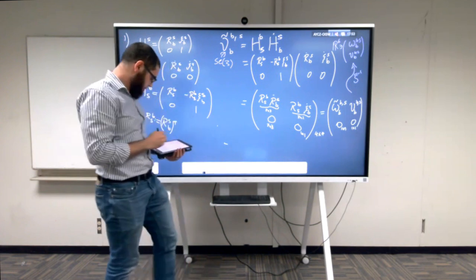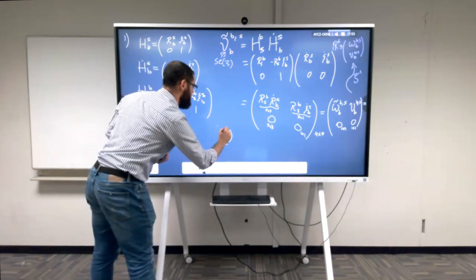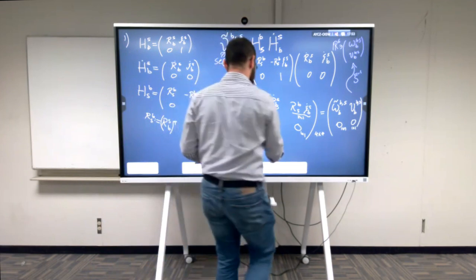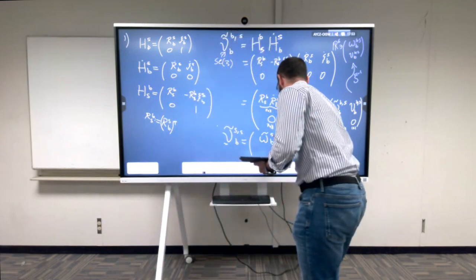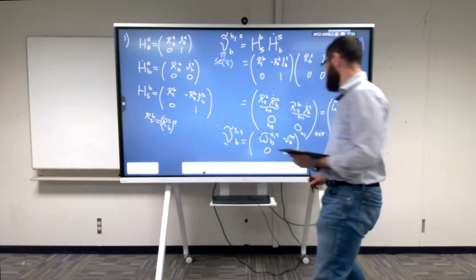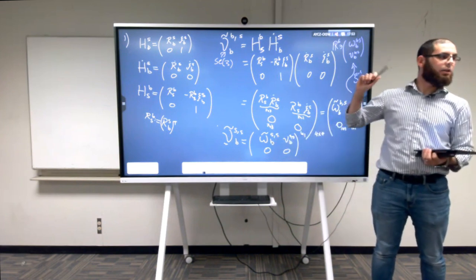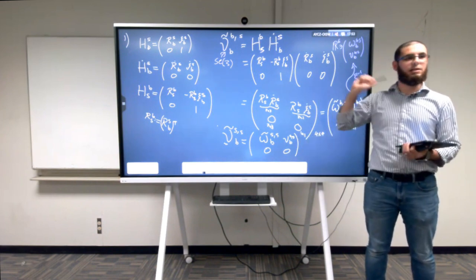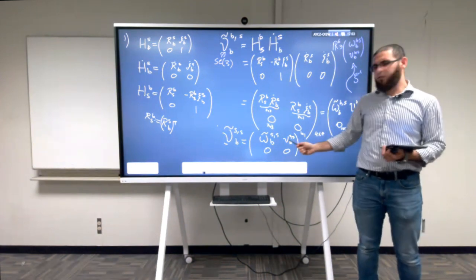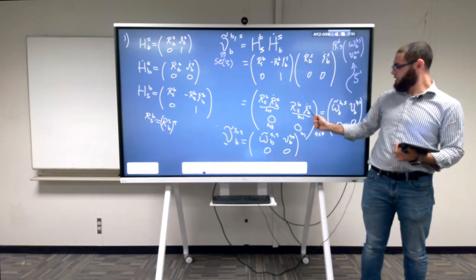This something else, even though it will have different relations, so this V tilde of B with respect to S expressed in S will have omega tilde B of S with respect to S, 0, 0, and VB SS. So again, we're going to have some angular velocity expressed in the stationary frame and some linear velocity expressed in the stationary frame. Now a question to you. Think about it for a second. The linear velocity expressed in the stationary frame, isn't it just this guy?